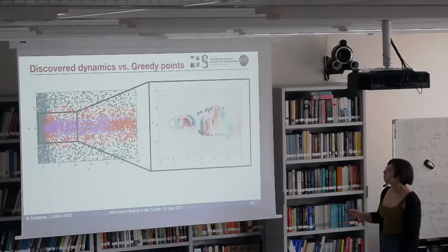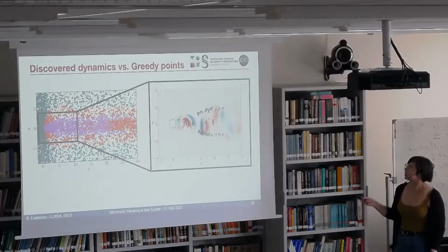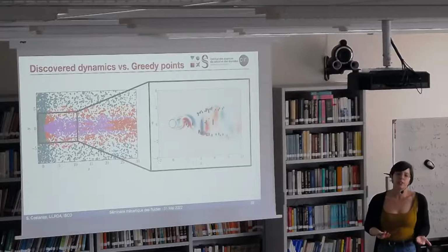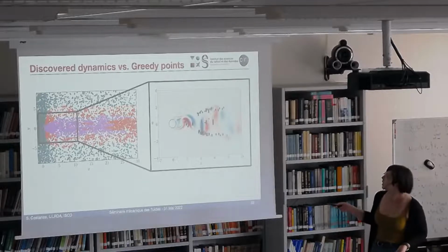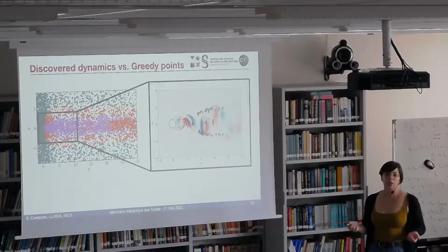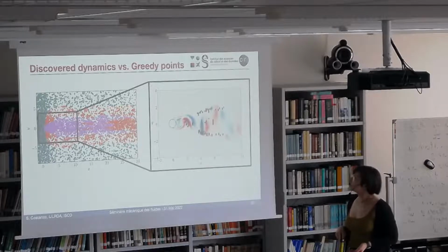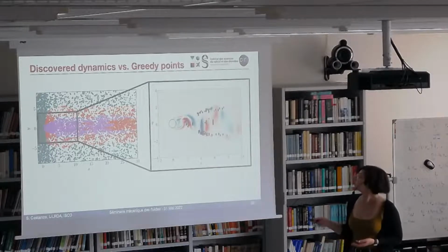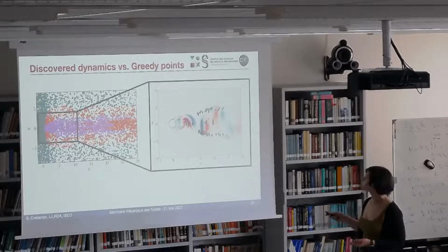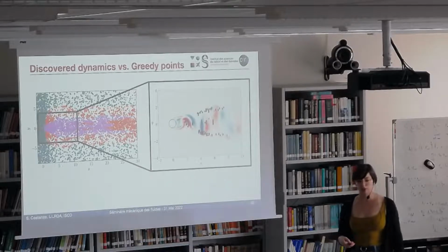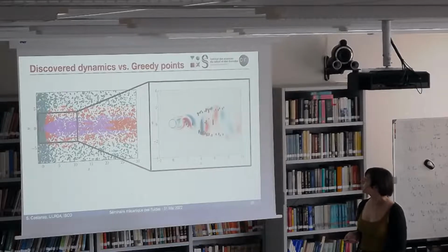So what we can do, before deciding if we want to use this reduced order model or if we are happy just with the simple Galerkin projection, is to check if we have nonlinearities, what kind of nonlinearities we have, and to restrict the search domain for the greedy points to the nonlinear area, reducing, of course, the dimension of the matrix that we use in the optimization problem for the Gauss-Newton tensor approximation.